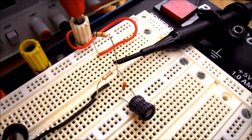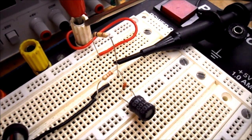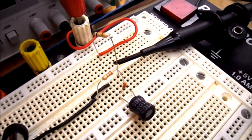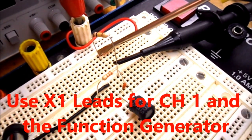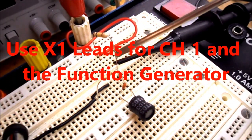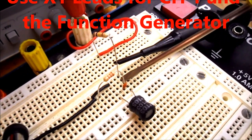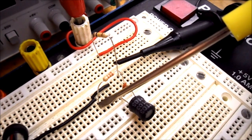So looking at my circuit, you can see that the red terminal that comes from the function generator and channel 1 of the oscilloscope goes to the input of my 100K ohm resistor RS. The other leg of RS goes to my 2.2K ohm resistor that goes back to the common of the function generator.